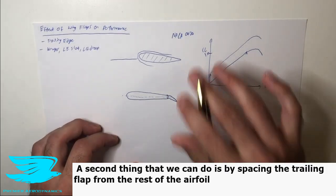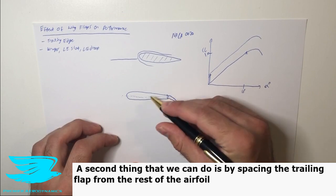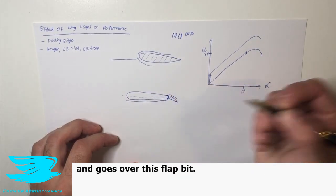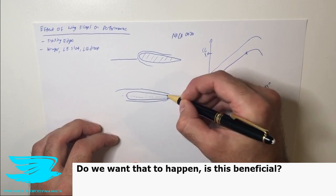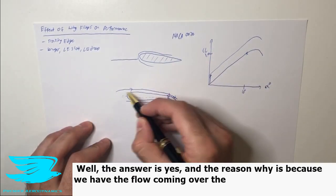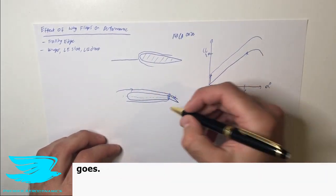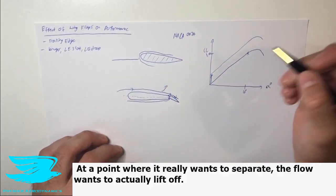A second thing that we can do is by spacing the trailing flap from the rest of the airfoil, we can actually get this flow coming here, and it shoots through this part here and goes over this flap bit. Now, why do we want that to happen? Is this beneficial? Well, the answer is yes. And the reason why is because we have the flow coming over the airfoil to begin with. And as it goes over the airfoil, it loses energy the more it goes. And it gets to a point where it really wants to separate, so the flow wants to actually lift off.